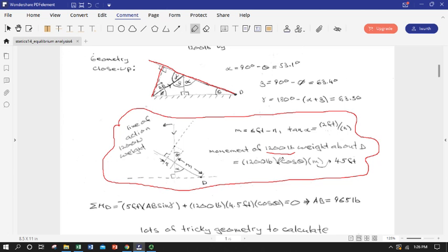So this ends up being our force, and this distance m from the hinge times cosine of theta, which is this angle here, ends up giving us our perpendicular distance of the force. And I won't walk through all of the geometry. You can do that if you would like to, but it took some careful considering of the problem's geometry to do that.